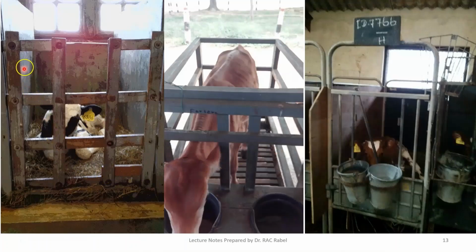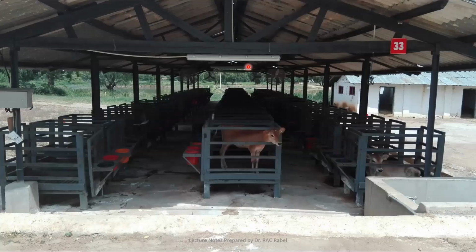But again, like I said, I might give this as a spot exam and ask you to guess where this is. If you say this is Ridhyagama, that's a poor guess, because in Ridhyagama or Hambantota or Mulativu or Jaffna, you would not build a calf pen with minimal ventilation. See, minimal ventilation, right? You have these brick walls on three sides and only the front door is open. Whereas this one is open from all four sides in warm weather. So these are the things you need to take into consideration.